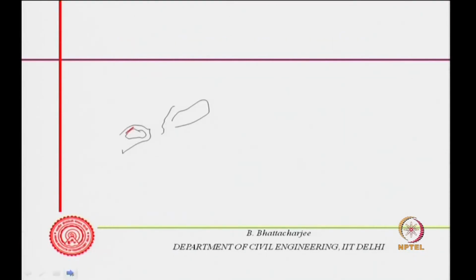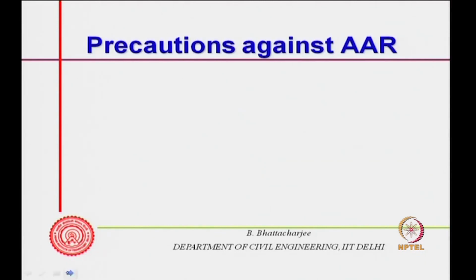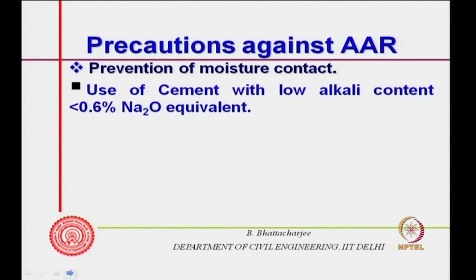Normally, aggregates are tested prior to their use, and then you try to eliminate the kind of aggregate that can cause the alkali aggregate reaction. So far we talked of alkali silica reaction. There is another kind, I will come to that later on.